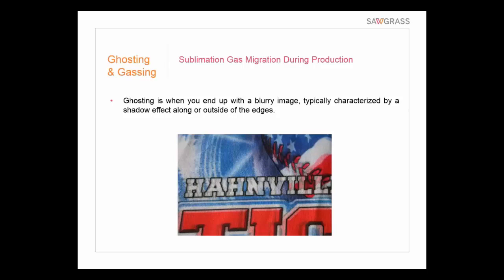When can that happen? When you open the heat press. That's pretty much the only time that can happen, unless you preheat something and drop a transfer sheet on top of it, then it can start ghosting. But provided you're doing things the right way, the only time you really see ghosting is when you open the heat press. When you're putting pressure down on the products and the paper, your pressure is holding everything in place, but it's actually compressing everything.